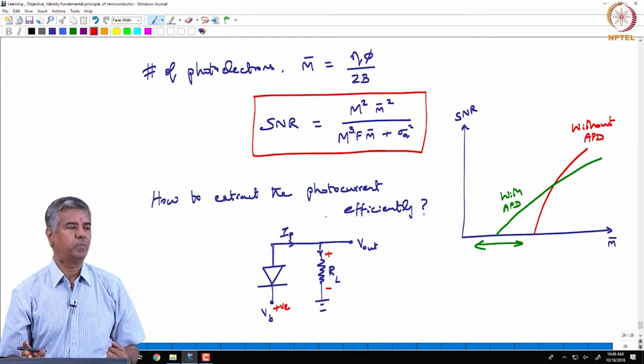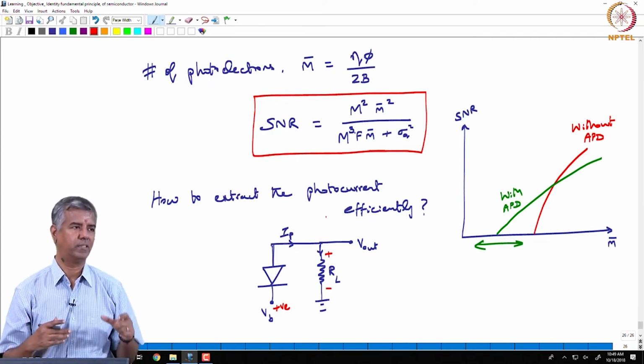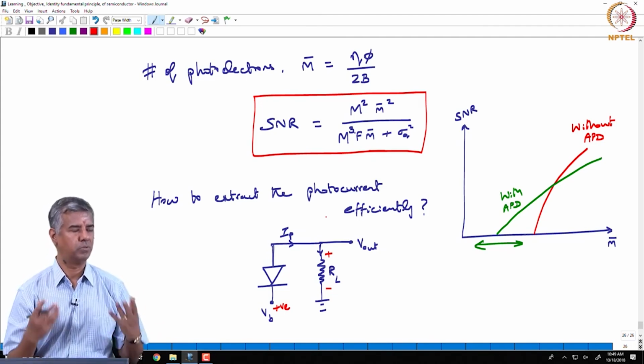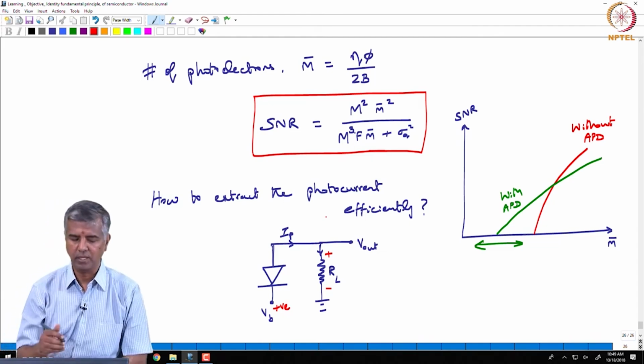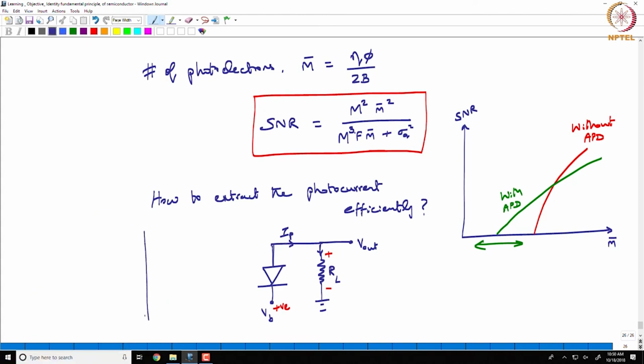So, that is actually going to be a problem, because if it is counteracting the reverse bias, then the effective reverse bias voltage that the photodiode is seeing is going to keep decreasing as you go to higher and higher photocurrents, as you pick up more and more light. Okay. So, let us just represent this through what we were previously looking at as your IV characteristics, right. And what we said previously is the IV characteristics are like